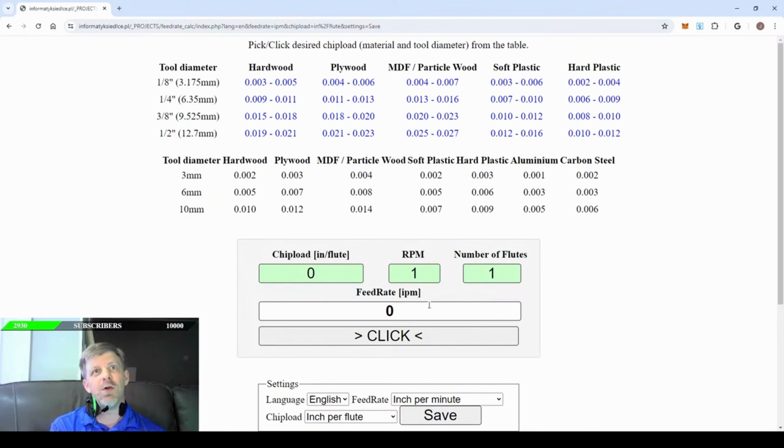So if you notice that you have a lot of wood bowing or warpage after your cuts, this is because a lot of excessive heat is staying in the material and the bit.